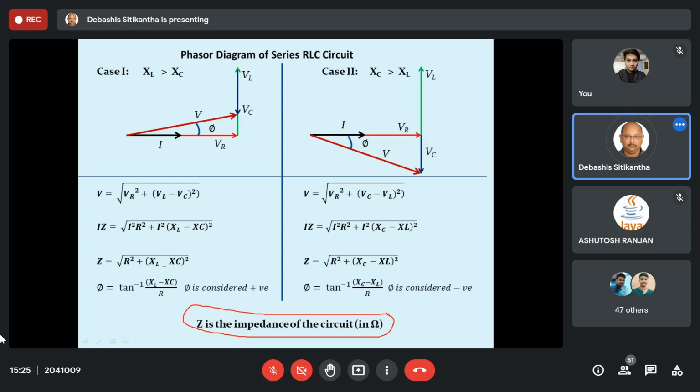It is because when the capacitor is getting a current voltage, it is building up an electric field, and this electric field is producing a voltage across it. Now this voltage is opposing the main cause of it, that is the applied voltage, and thereby it is opposing the current. So in all these cases, whether it is R, XL or XC, they are nothing but opposition to the flow of current. The only difference is the way they oppose the current.